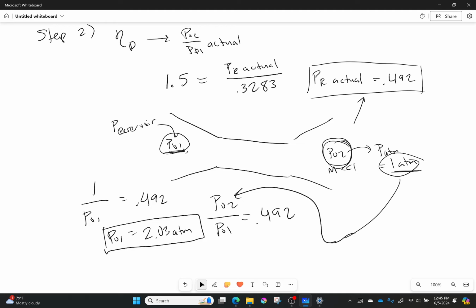Okay, so we did it. We figured out for this actual diffuser, where there would be shock waves in here, what our reservoir pressure would have to be to make it actually run. Because remember, you can't just run it with any particular pressure. What pressure you choose will determine if it goes supersonic, we're talking about a nozzle, if it runs at all, or if it ever reaches that choked flow, which we're looking for in most of these cases. So cool, we did it. Well done.